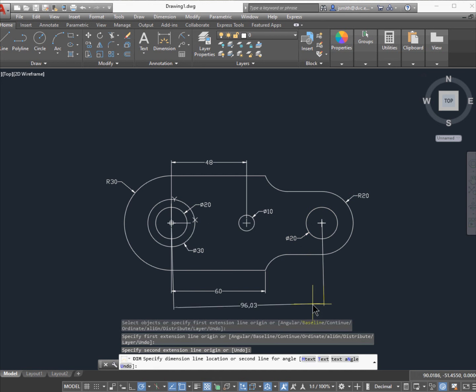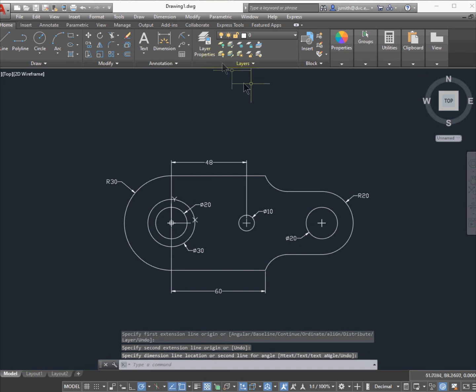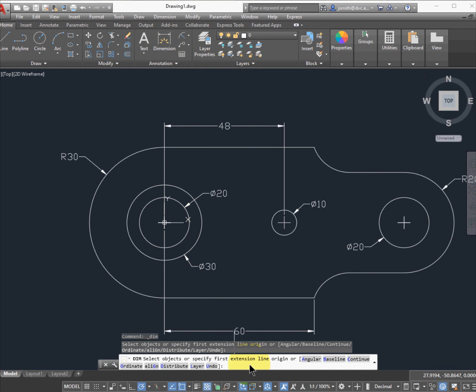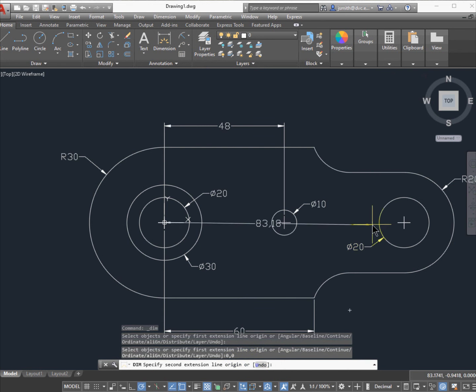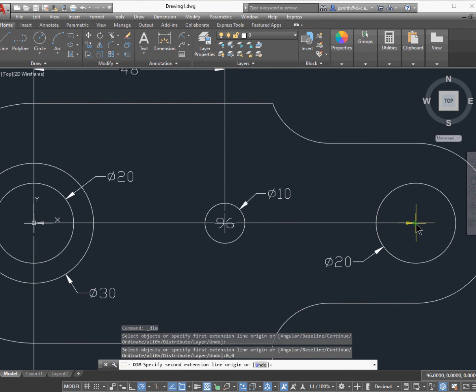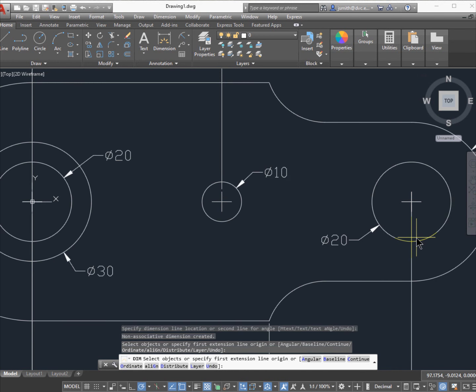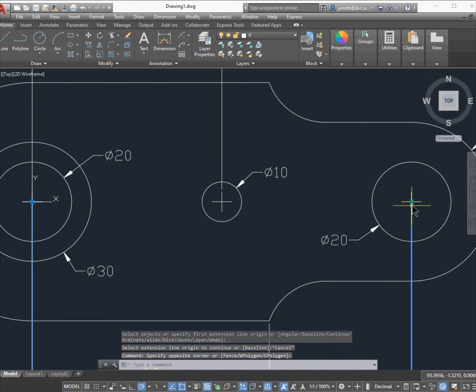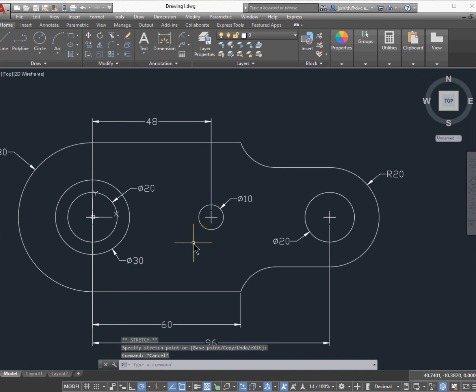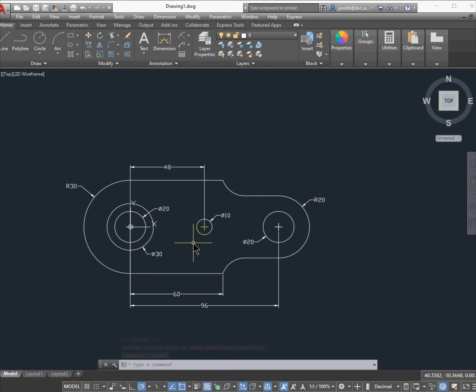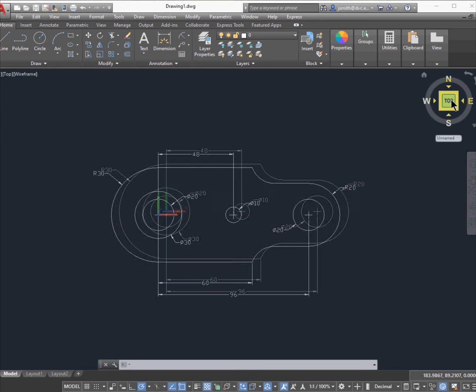And when you are drawing parts, you generally dimension from the center, and you can notice that one's off there, so let's just do that again real quick. That's why it's always best if you can type in the coordinate rather than snap. The snap tool is much more convenient, but sometimes it can get a little sloppy, so you've got to be careful. And then I can always go back in and drag the line down and verify the dimensions, and so I've got that gap. Alright, so that looks good.